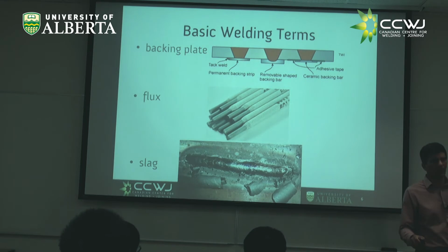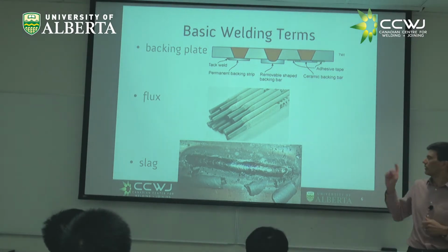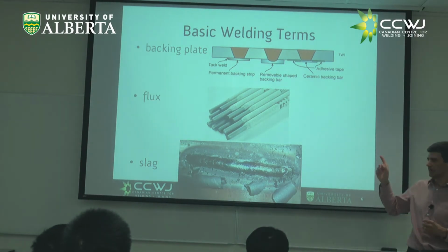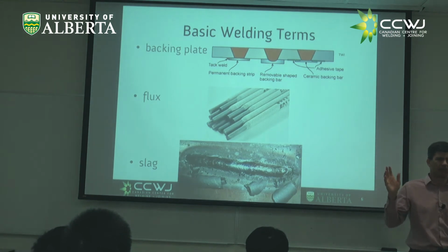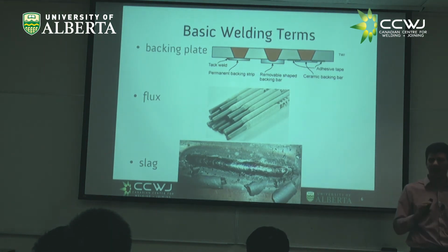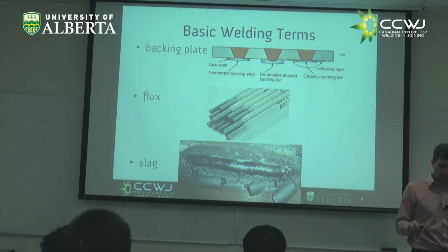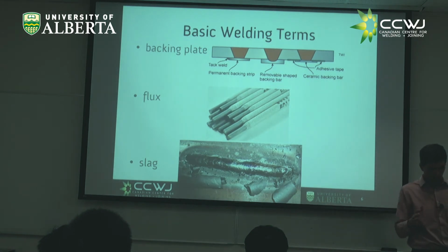The other way about it is to have what is called a shielding gas, and I don't have this listed, in which you blow argon or helium, right? Or whatever thing that is expensive and inert, right? And that would protect your weld. And then you don't need to chip off anything, and it looks very clean and easy. But the gas is expensive, and also you have two other problems. If your weld has a huge molten tail, it's likely you'll not cover it because the gas is concentrated in an area near the weld.